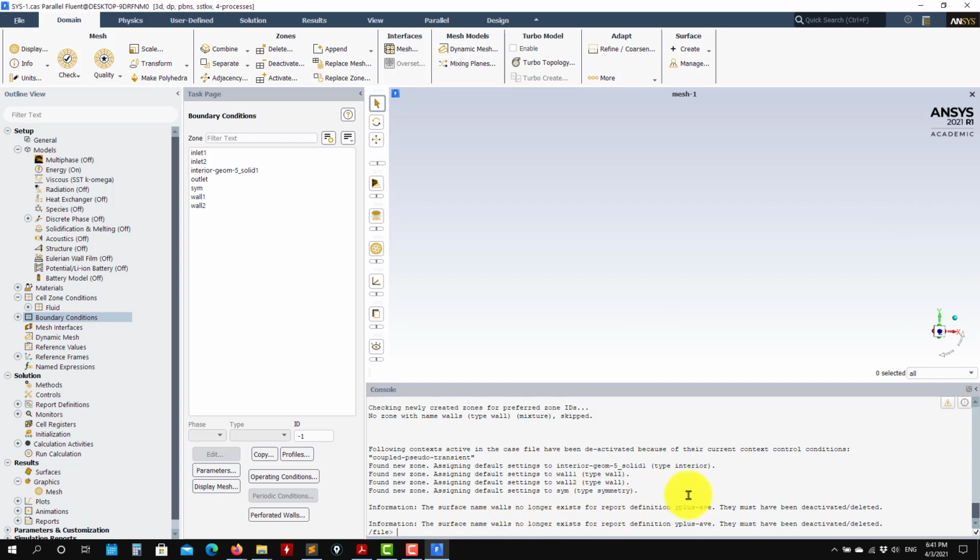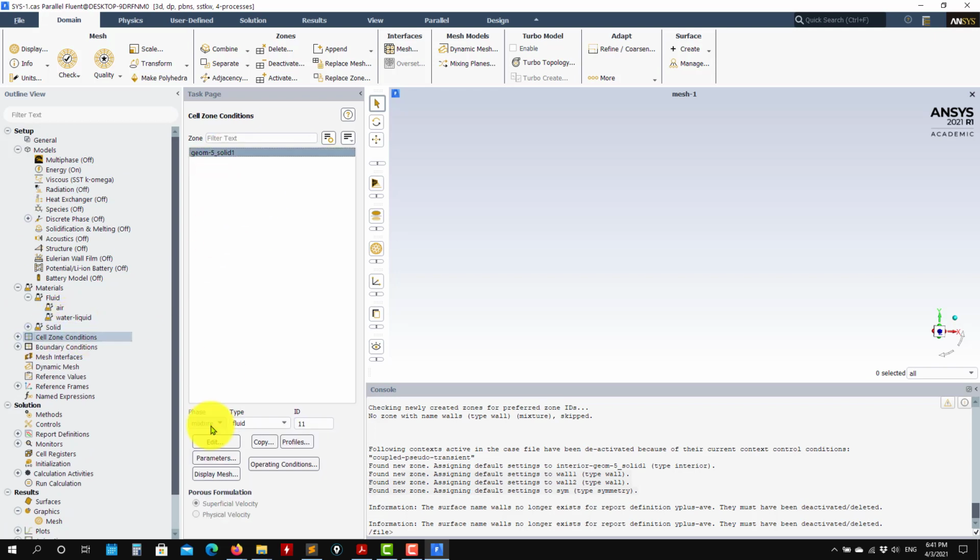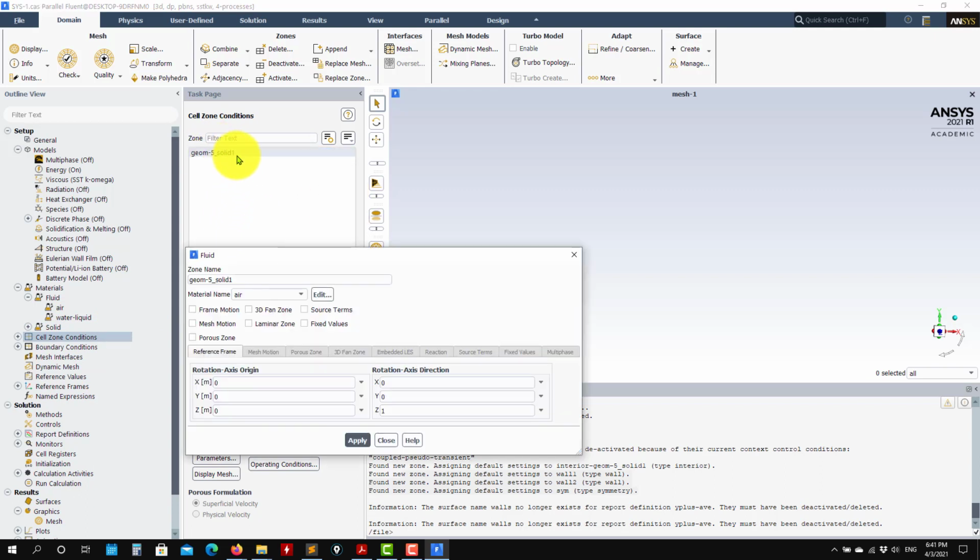It's going to give you a warning because probably you have different names of the patches and the domain. That doesn't matter, you can do it manually, but it's important to see that now my setup here, see that energy is enabled. You go here, you enable the water liquid. You need to go here because likely you also need to assign the model because you have a different name of the whole domain. See that now water is enabled here, you have water.